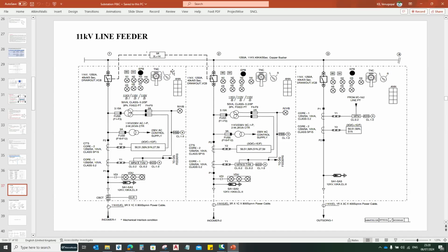And similarly, I also provided mechanical interlocks. It means that in this switchgear cubicle, I have two incomers and one outgoing. In these two incomers, one will always be in on condition, and the other will be like a standby unit. For that, the interlock I'm doing is providing two locks plus one key. So here I'm providing one lock, and here also one lock, but only one key.